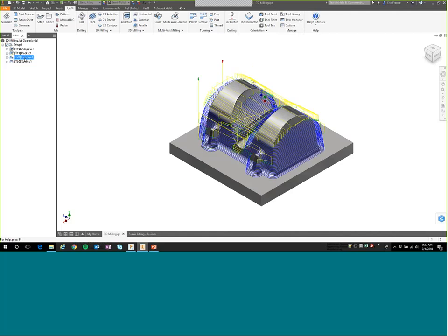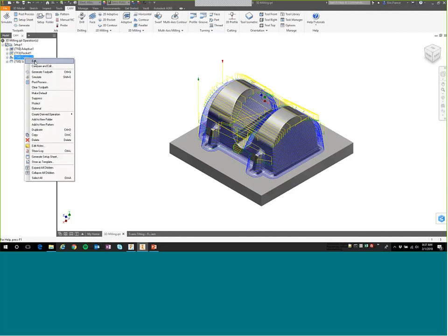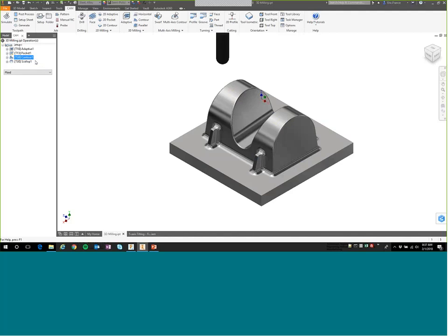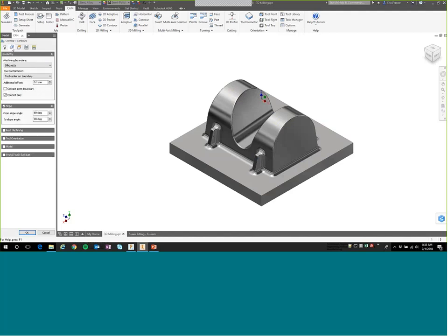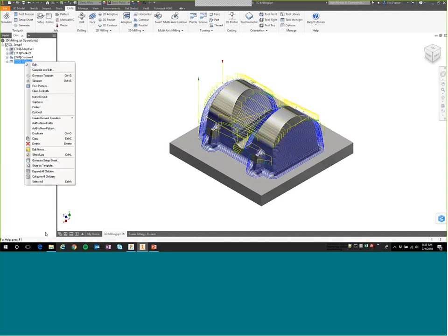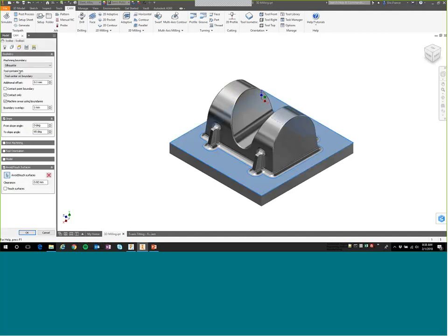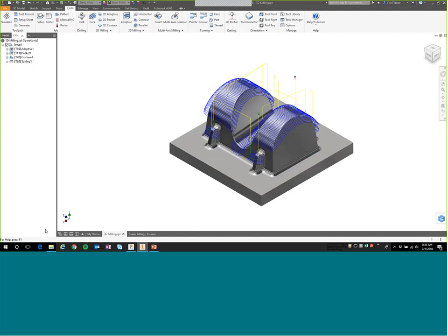But what I want you to notice in here is that we're using some settings in the tool itself to do some containment. That contour isn't going all the way up. It could with the default settings, but we have the ability to identify slope. So we're focusing on from 90 to 60-degree slope for the contour. And then for the scallop, we're going from 0 to 65. We want a little bit of an overlap so that it handles that appropriately. But being able to control that, again, contains the tool to those particular areas.